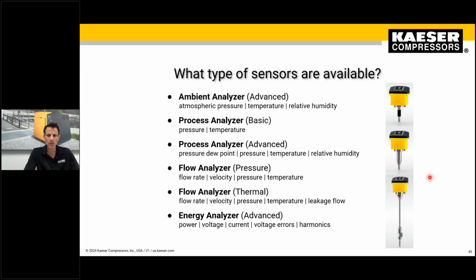When it comes to operation, you're going to have measurements within the compressed air system. So that'll be your piping. Like we discussed already, you're talking about pressure and temperature maybe. Pressure dew point is also a big key item. As Pascal had mentioned in his presentation, it gives you an indication of whether or not you're moving towards perhaps a situation where one of your dryers may have failed, or perhaps your desiccant needs to be replaced, and so on and so forth.